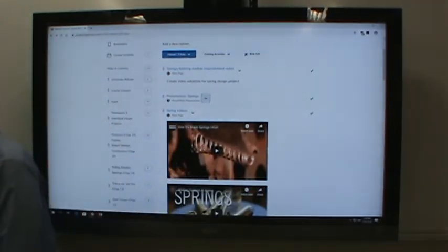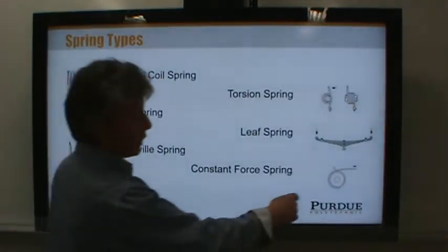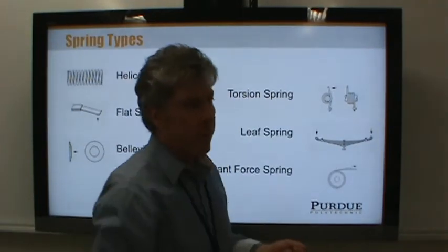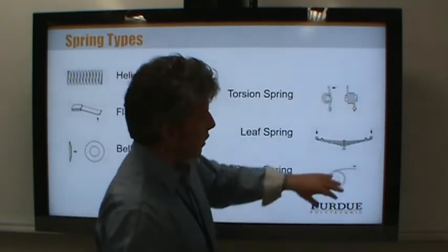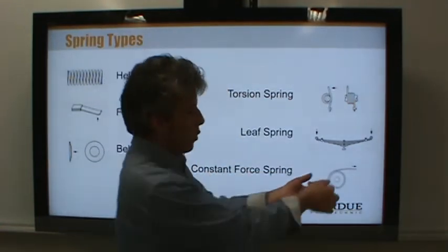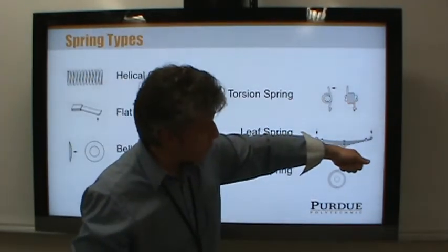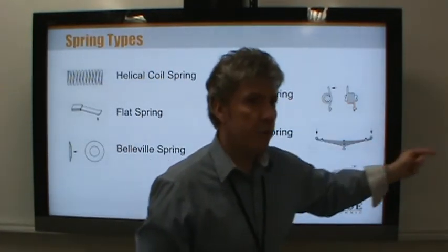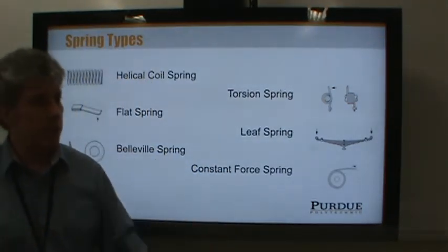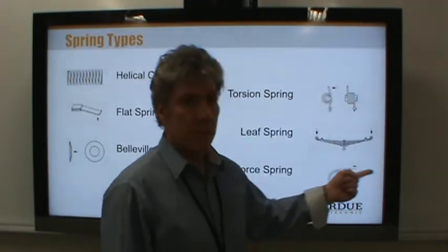The way these things work is typically you've got another take-up reel over here, and as you wind it, you've got a ratchet and ball that keeps it from going backwards, at least until you turn the flashlight on and release it and allow it to go backwards. But the amount of torque required as you deflect this spring does not change. In other words, if you were to just grab a hold of the end of this spring and pull, the force versus deflection would be constant. You deflect it more and more and more, and yet the force remains constant. You're still putting energy into it because the force times distance is work, right?